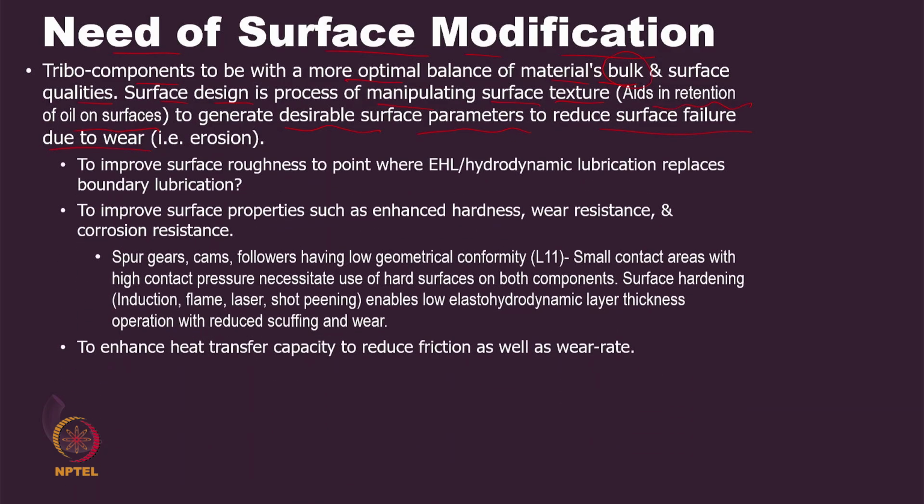Another reason why we require surface modification is that many times we want to improve the surface roughness, so that we obtain more or less EHL or hydrodynamic lubrication.